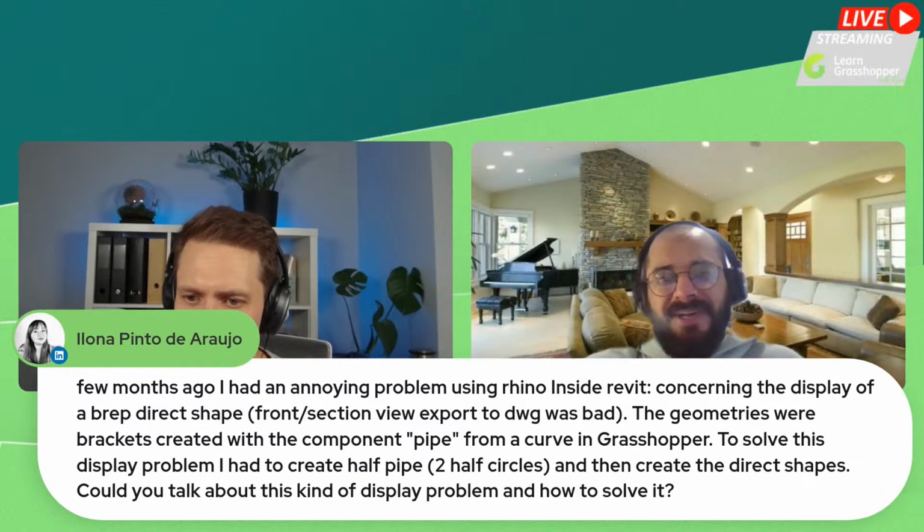No, because I have created these, if I have shown you this tower, these were the curved shapes. So I didn't have that problem, but what I remember from this Rhino.inside.Revit community, a lot of people have this problem. And Scott Davidson said maybe there's a problem with the tolerance. If you have different tolerance in your Revit and the Rhino, maybe because of that you have these problems. So maybe try to change the tolerance and regenerate the family. Maybe you will find a solution.